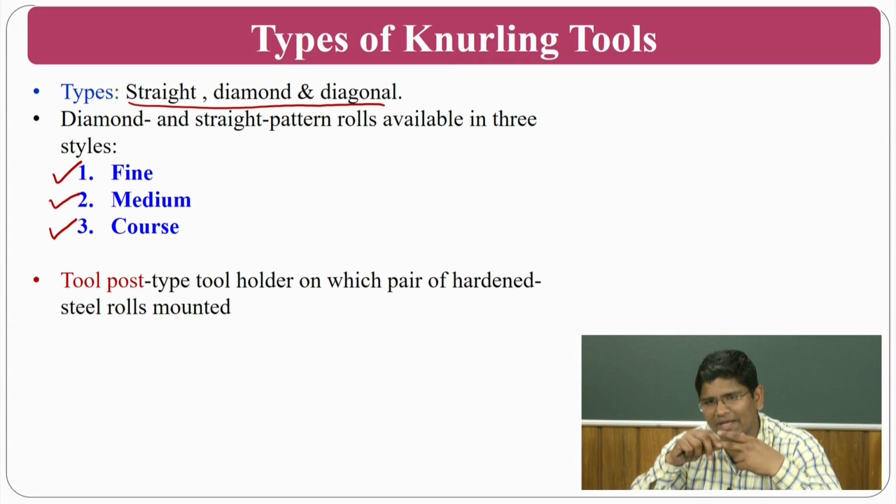Okay. So let me repeat, you can change the surface engineering by a fine knurling operation, if it is on a plate or if it is on a cylindrical surface, whatever you want to do. The second thing is to just generate the fine pattern, then you cut using the same cutting tool and compare with the normal turning operation. I mean to say, if you take a cylinder, first generate the fine knurling, then do the machining operation and measure the cutting forces as well as temperature.